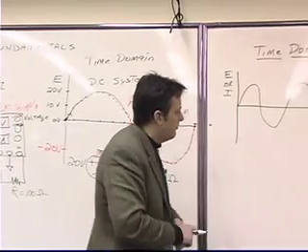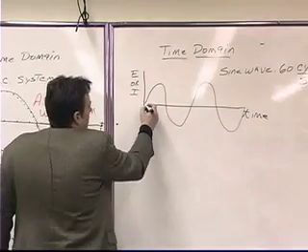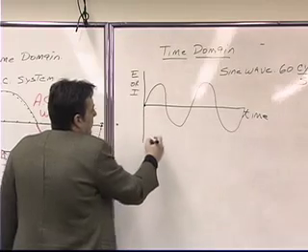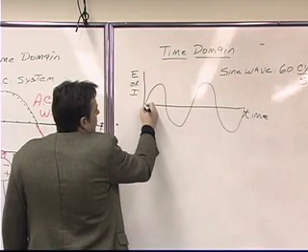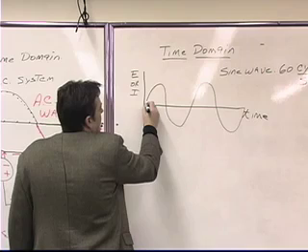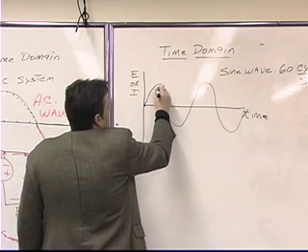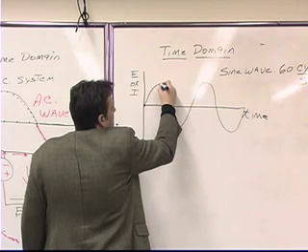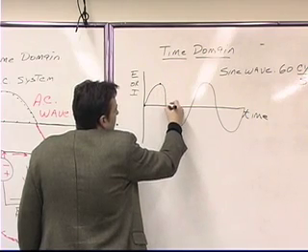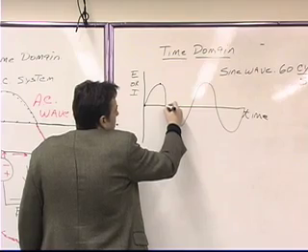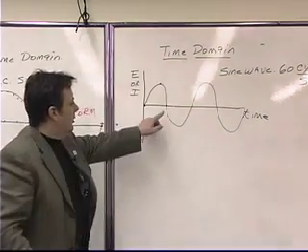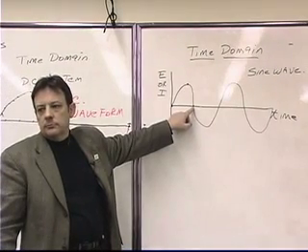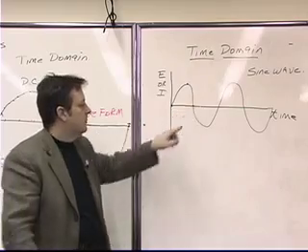Exactly. All right. So coming back again to our definition of one cycle, if this is the point at which we started going positive, follow the waveform. It's going positive, it reaches a peak up here, and then it starts going negative, and then it goes through 0. We call this point right here a 0 crossover.